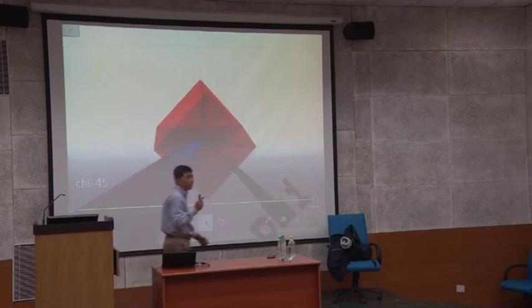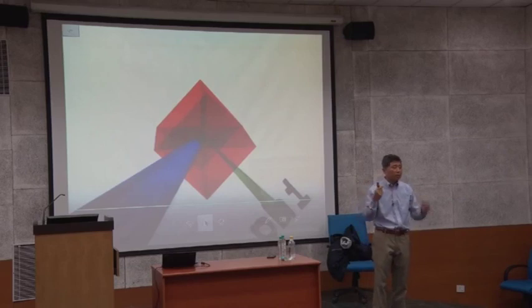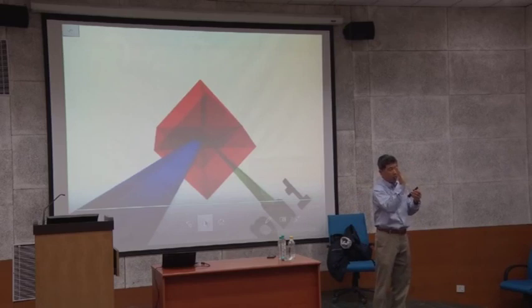So this one comes every 90 degrees. This peak is not facing the surface, it is off axis. This is called an off-axis peak. And from those, you will be able to know the symmetry of your material. If your symmetry is perfectly cubic, then you see a peak every 90 degrees. If you have 2-fold symmetry, you will see every 180 degrees. If you have 6-fold symmetry, you get every 60 degrees. So with symmetry, you can actually see that.